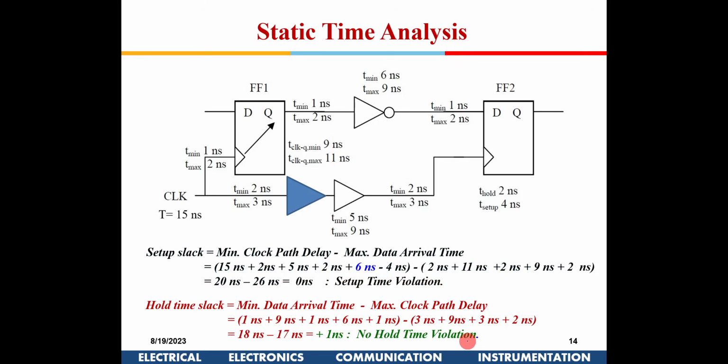Here I guess one option is to insert a buffer out here, but if you insert a buffer here, I think there will be a hold time violation, correct? Yes. Here there could be a hold time violation. So you have to see what is the best available option. You have to see all the constraints and accordingly do that.